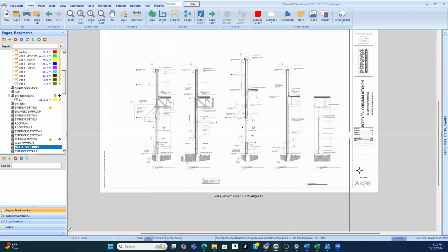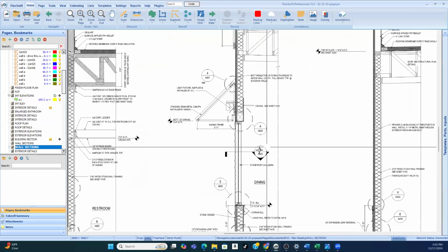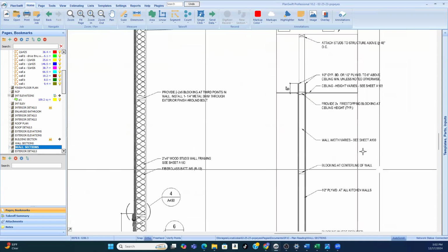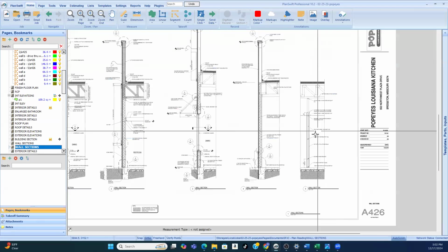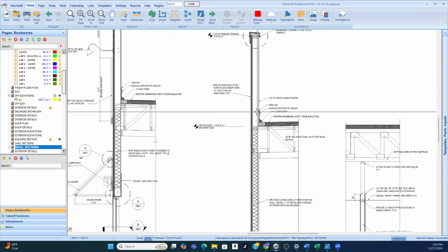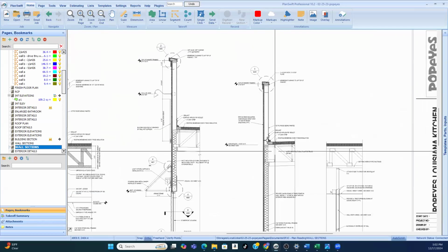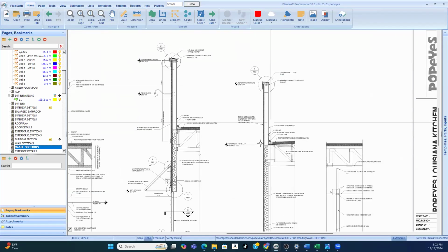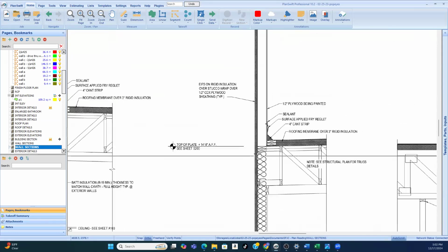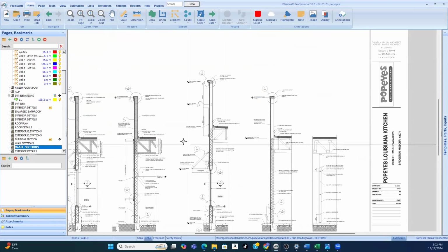See, these are all section views at different places: section view at the window, section view at the bathroom, and section view for an interior wall. This is the parapet wall, the amount of wall above the roof framing. I know that doesn't get insulation because this represents insulation. I know the parapet wall is not insulated because I have a very good section view.